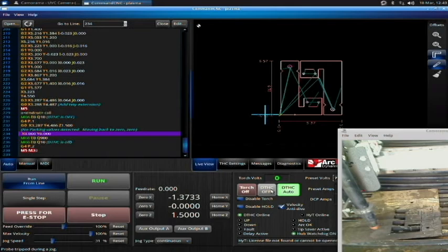So, those are two examples of an error on a cut. Okay? So it's very important. I recommend you practice those over and over. And you can do the misfire in a dry run sequence. Okay? You can't do the loss of arc during a cut in a dry run. But take some time, do some scrap material, practice that sequence of events.